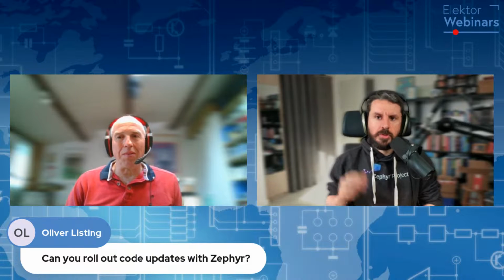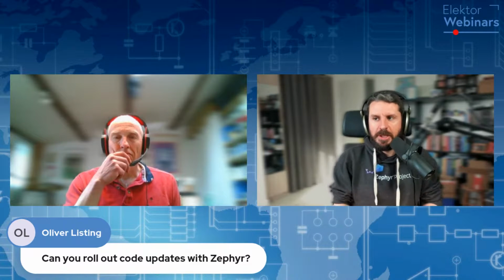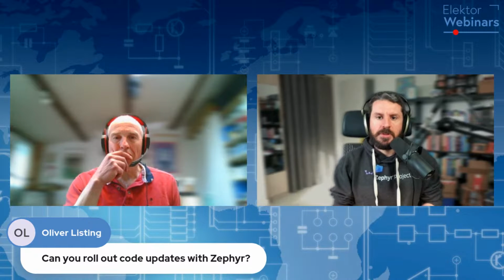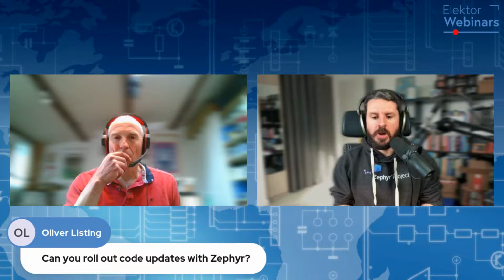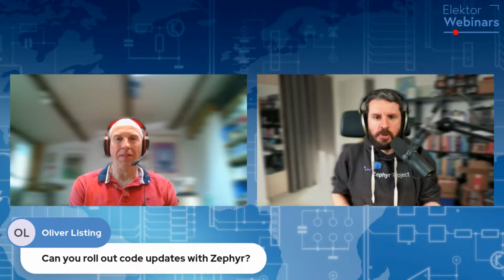Yeah, really good question. So Zephyr works really well with a kind of dedicated bootloader. I mean, not dedicated, but a bootloader called MCUboot that happens to work really well with Zephyr. So basically, when building your Zephyr application, thanks to West and all the tools that are integrated with Zephyr, you would be able to build not only your app, but the MCUboot bootloader alongside it, flash the whole thing to your device, so that when you power on the device, it's MCUboot being the first